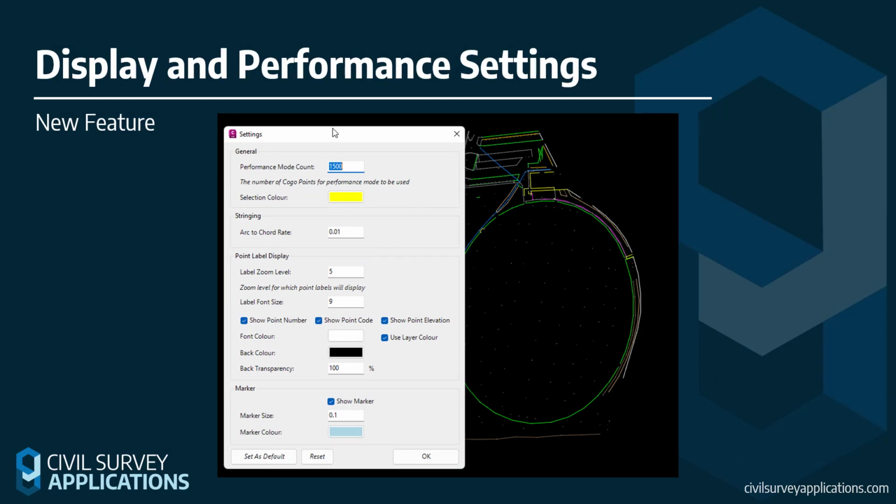Under display and performance, we have actually added a new settings tab. This allows you to change the display settings within the software. Now this came about as one of the biggest slowdowns for larger jobs is the labeling, and what we have applied here is the ability to modify that labeling. So you can see here we have a performance mode that controls the anti-aliasing that's used for the points, basically decides how many points it takes for that to kick in.